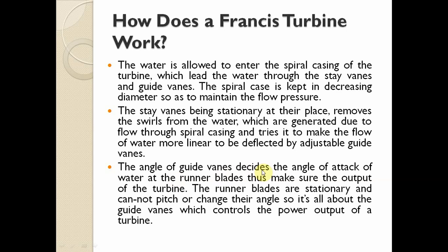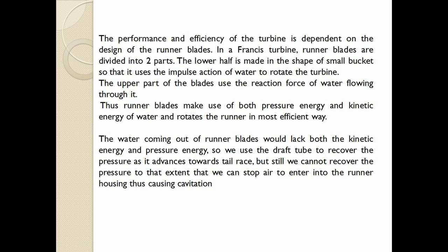The angle of the guide vanes decides the angle of attack of the water at the runner blades, thus making sure of the output of the turbine. The runner blades are stationary and cannot pitch or change their angles, so it is all about the guide vanes which control the power output of the turbine.